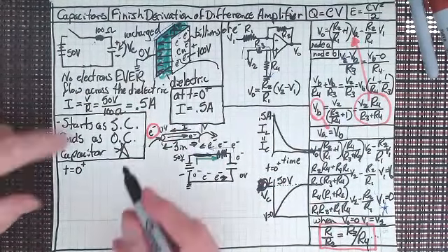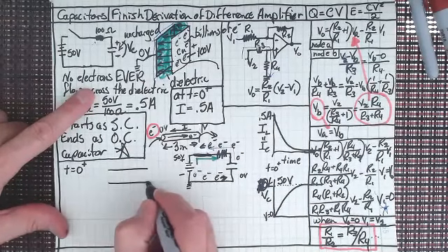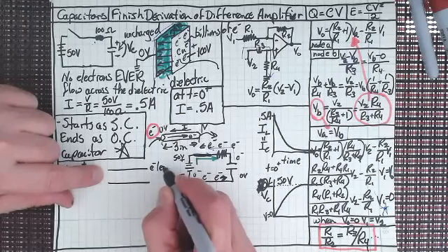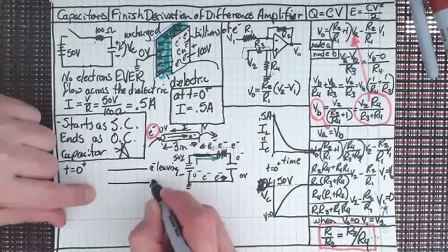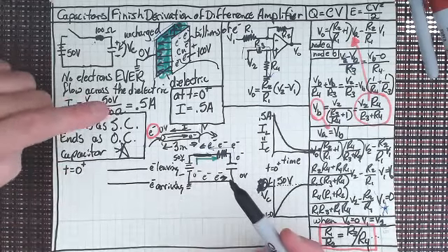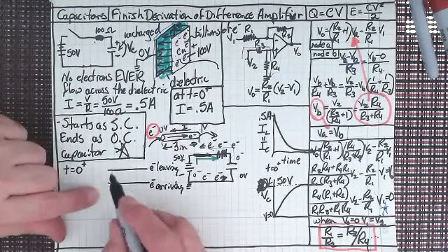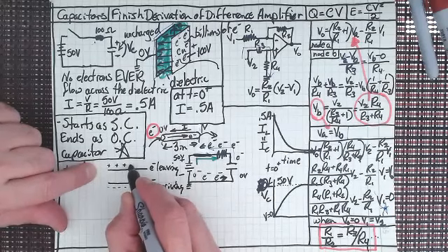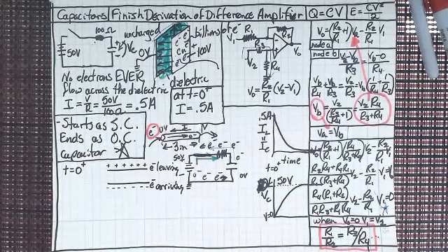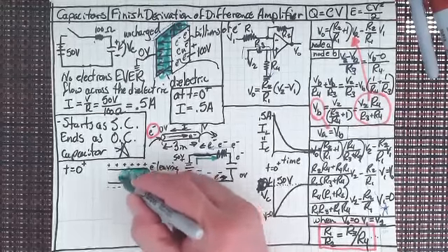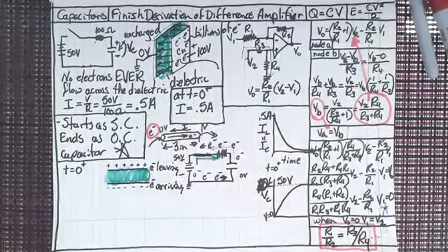If we look at what's going on inside, let's blow that capacitor up a little bit, and look. So the electrons are leaving this side, and the electrons are arriving at this side. So I'm going to have a negative charge over on this side eventually, and a positive charge over here, because all the electrons left here. So all that's left is the positive charge, right? And on this side, all that's left is the negative charge. Has any electron ever crossed the dielectric insulator boundary in between the two? No, it never has. It's never done that.